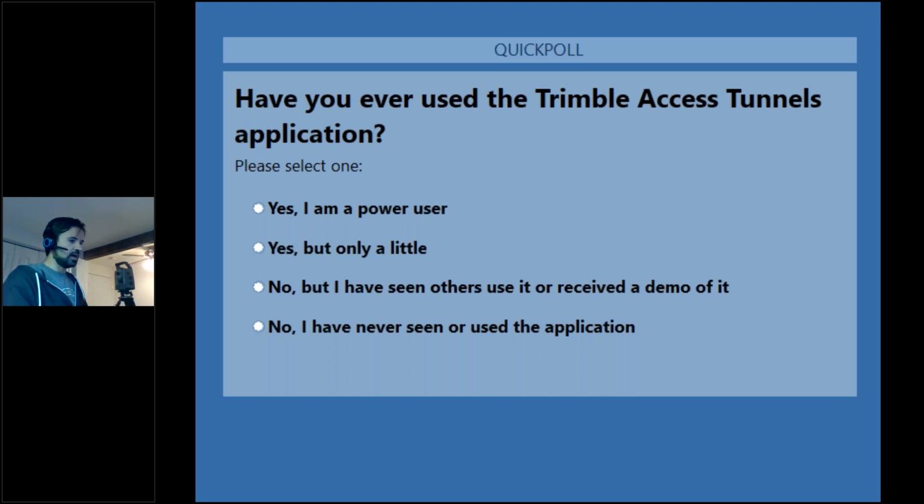The reason I'm using it in this particular demo is that in NATM tunnels you're doing a lot of stakeout of key features, things like rock anchors, blast holes, and all that. One thing that is essentially critical is to have a laser pointer, and that's why I'm using the S9 today. That's not to say you couldn't use the SX10 for the exact same thing. The only challenge is the SX10 doesn't have a laser pointer.